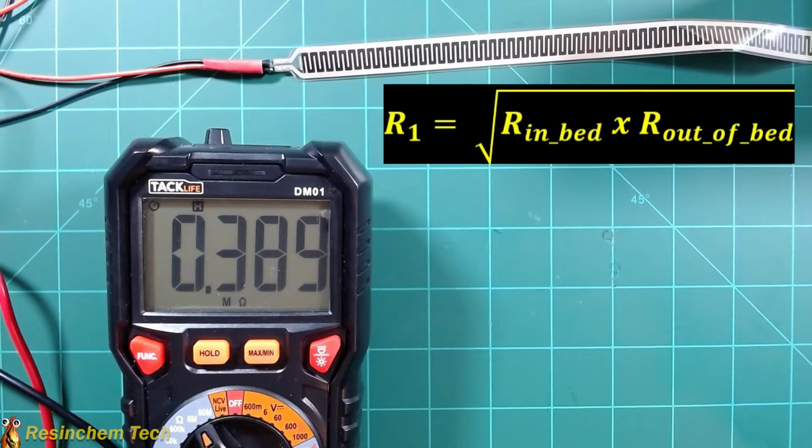So for me, and again, your numbers will be completely different just based on the weight of the mattress, how you are opting to lay when you're in bed, I had an average resistance of about 3 mega ohm when the bed was unoccupied, and a resistance of about 500 ohm when I was in the bed. That is an average taken over multiple readings.